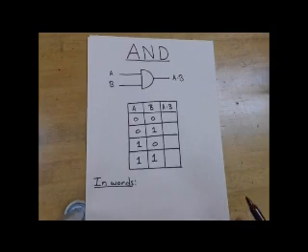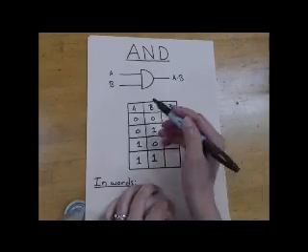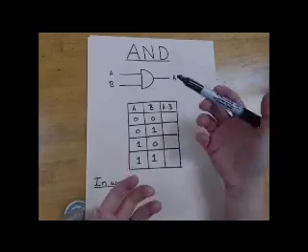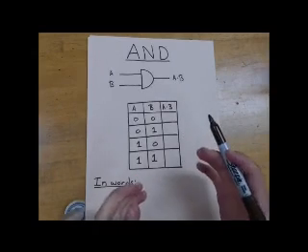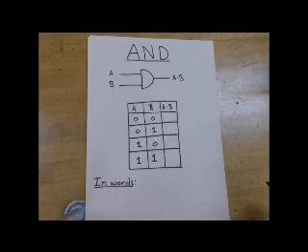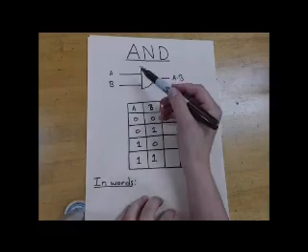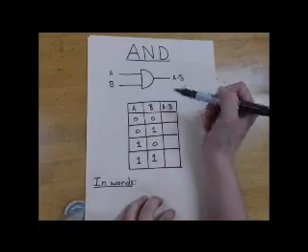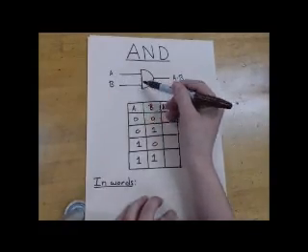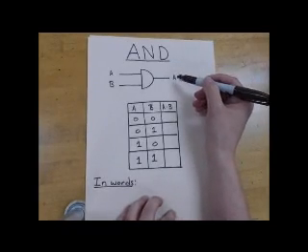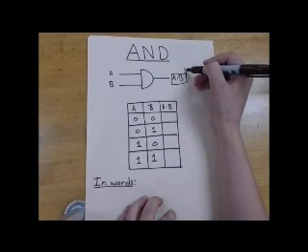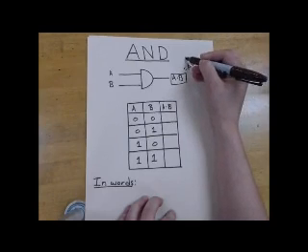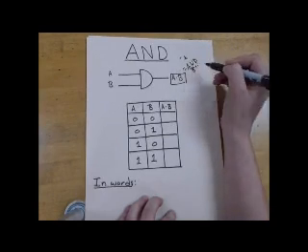So what these gate circuit diagrams are, we can break them down into, well, what do these gates do? A logic gate is simply a way of taking 2 inputs and manipulating them in order to get a desired output. So in this case, the inputs here are given by these 2 wires, and the output is given by this one. A and B are both inputs, and the output for an AND gate is given by A dot B. So this right here is what symbolizes AND. So this is read as A and B.